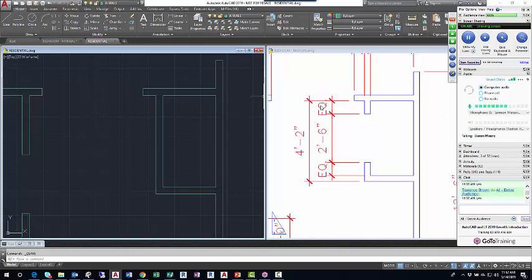Okay. So I had changed this in earlier versions. I don't like that EQ, but you're going to see it. You're going to see this EQ if you deal with site plans, maybe a little less. I don't deal with a lot of site plans, but if you deal with floor plans, it's a way to put information into a small space. The actual distance here is 8 inches, 8.25 inches, and it would be really hard to write 8.25 inches in that tight little space. So if you ever get a dimension that looks like this, it's EQ. It's saying from here to here and here to here are the same distance.